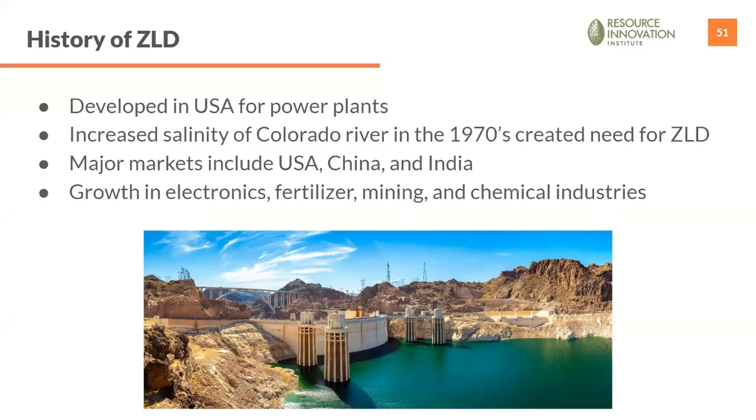According to the EPA, the majority of ZLD systems operating within the power industry treat blowdown water from cooling towers and boilers, many of them recycling over 99% of the blowdown water back into the cooling tower. Additionally, with increased freshwater pollution and salinity, there's been an uptake in ZLD adoption in the electronics, fertilizer, mining, and chemical industries.